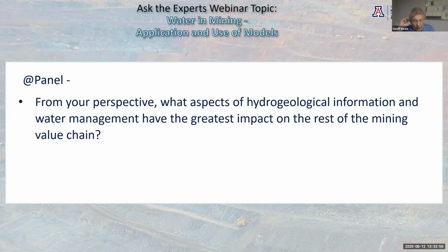Too often we put in our piezometers too deep to be of value to the geotechnical model, where more often than not the failures are relatively shallow. So many mine sites I go to, I tell them not to drill the piezometers so deep, and I've just written a couple of reports today to that effect. So make sure you focus your hydrogeological information on the known failure mechanism or area of deformation.